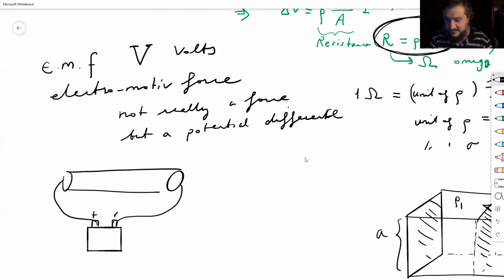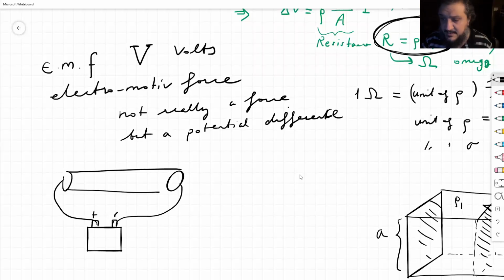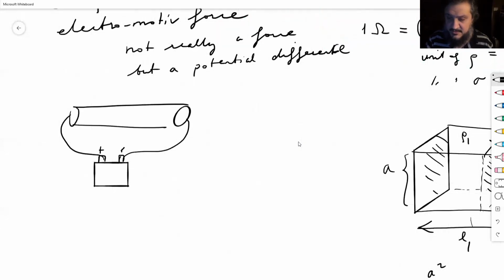Never try to short the terminals of your battery. Just because I drew it here, don't do it. It's dangerous. Why? You will have a huge current all of a sudden. It's going to create sparks and then maybe melt something and maybe even start a fire, or it's going to explode, who knows. It's not good.